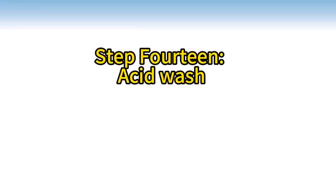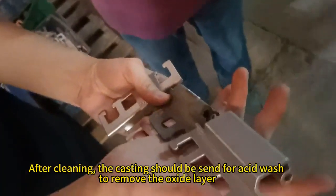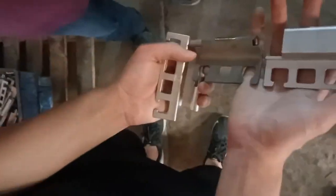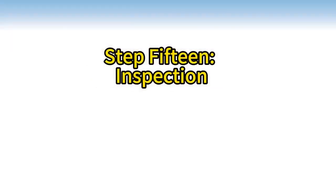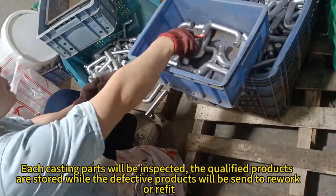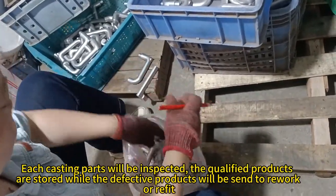Step 14. Acid washing. After cleaning, the castings should be sent for acid washing to remove the oxide layer. Step 15. Inspection. Each casting part will be inspected. The qualified products are stored while the defective products will be sent to rework or refit.